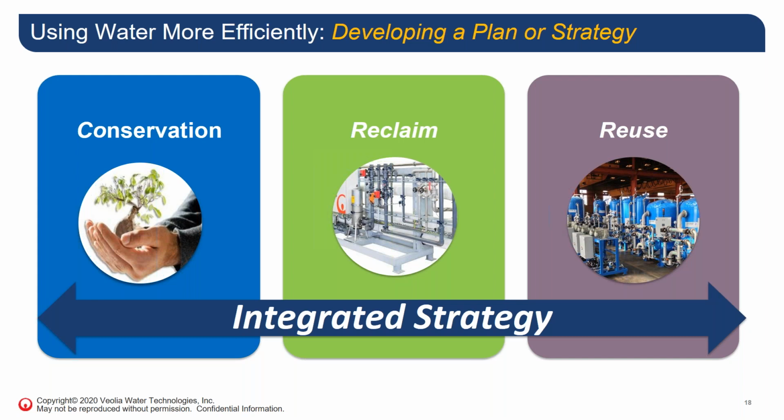For example, can once through pump seal water be collected and redirected back into a secondary usage with minimally increased costs? Can utility pretreatment rinse water be captured before the drain and used somewhere else in your plant? So the second bucket or pillar of the integrated strategy is looking for streams that already exist that could be reutilized or redeployed someplace else in your plant.